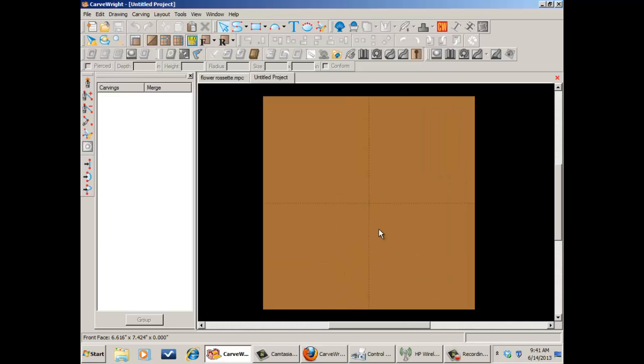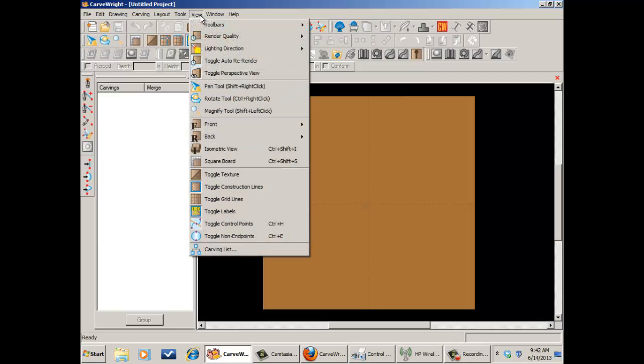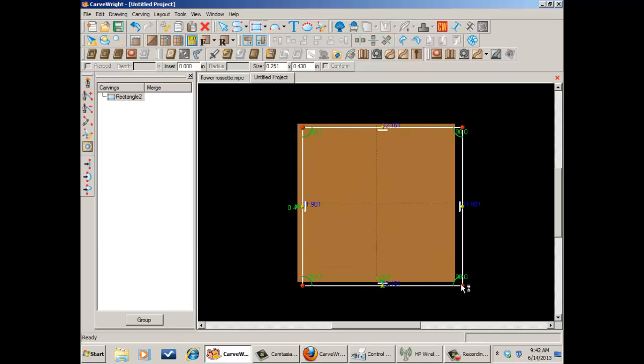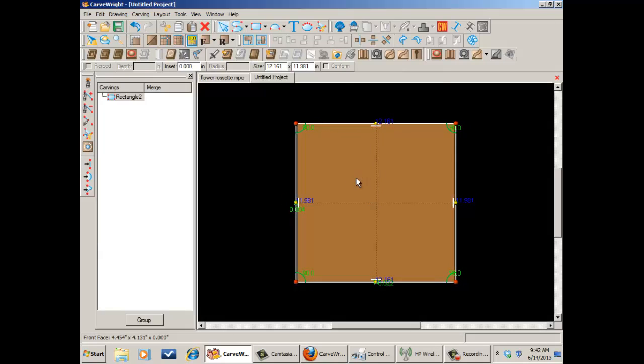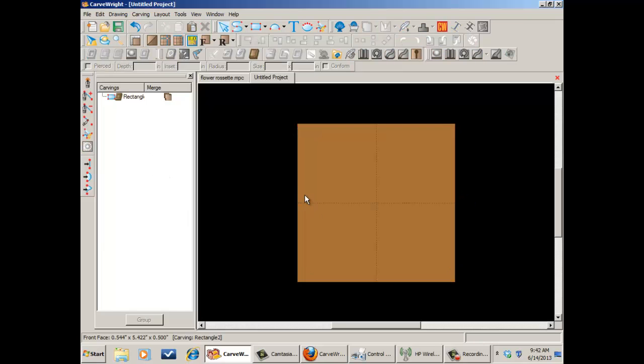Okay, so I'm going to create a new board. Again, this is my 12 by 12 pattern making board. You guys remember what the first steps are? Turn off the wood grain. Turn off perspective. Yep, and then create my rectangle to create my floor. And we'll set that to 1/2 inch deep. Good, everybody's awake and paying attention. I appreciate that.